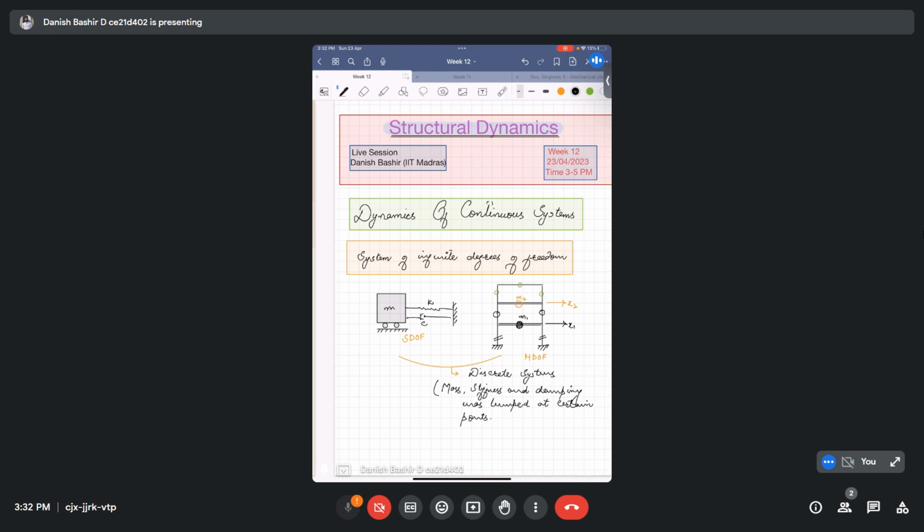Okay, so this was the case in this thing. In mass, stiffness, and damping, all the parameters are being taken care of. In mass, you usually have the geometric shape of the system. In stiffness, you have the material properties like Young's modulus and shear modulus, because those are taking care of the stiffness of the system, and geometry as well, because there is a geometric contribution to the system that comes from the geometry as well.